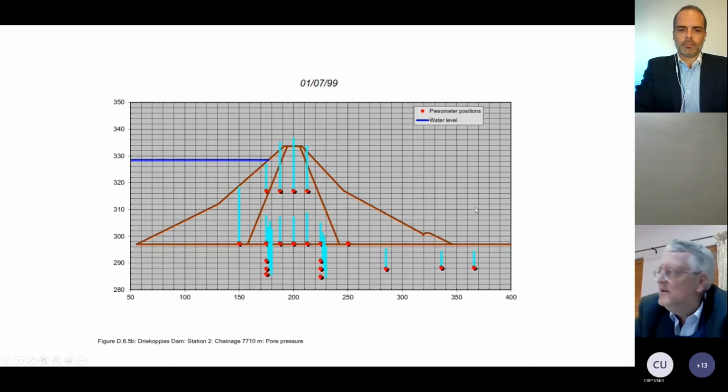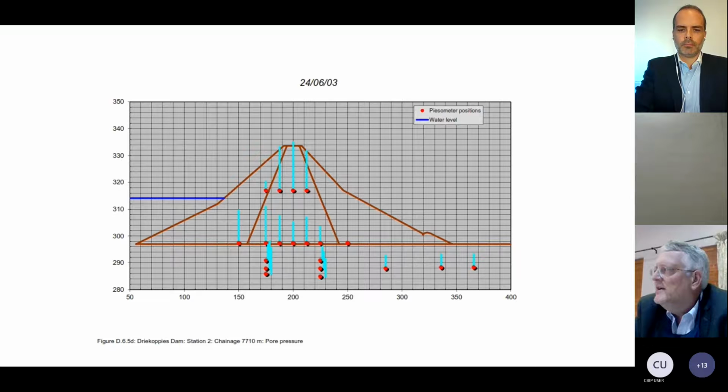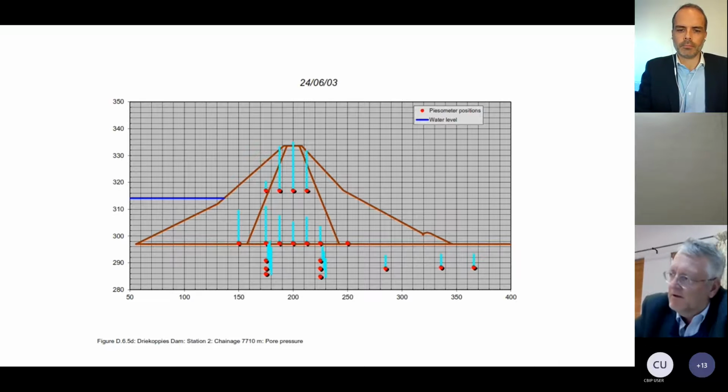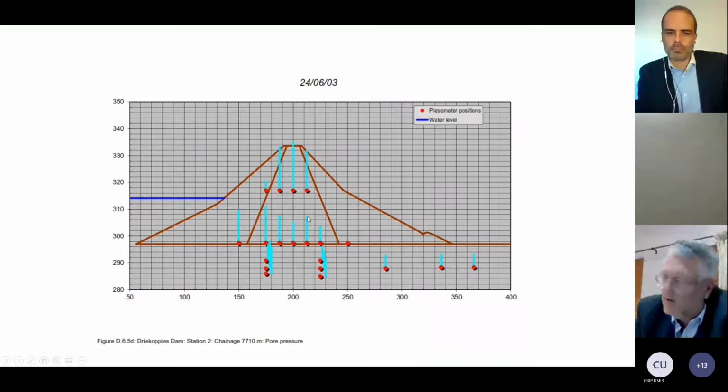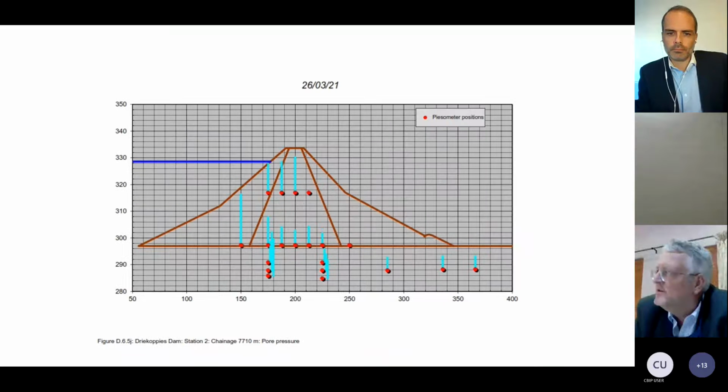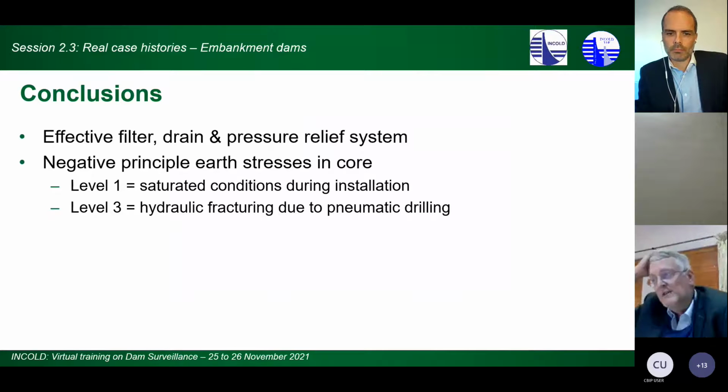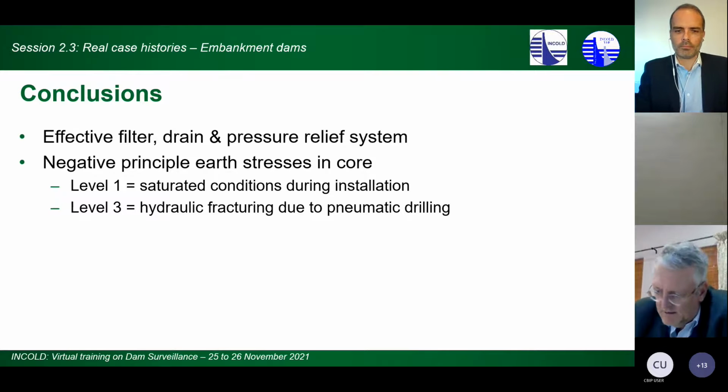That's what we're looking for, and it even decreased. So we conclude our grout curtain that sits over here is really effective, and we don't have a high risk of piping or internal erosion. So basically at 2 places we had negative earth pressures, and at level 3, the higher one, we had good records, and one can go back there.